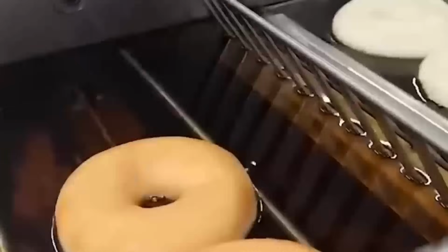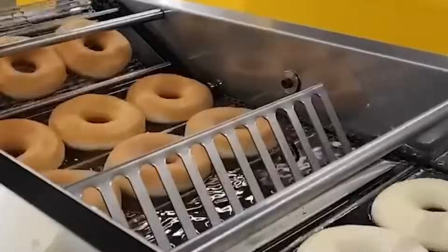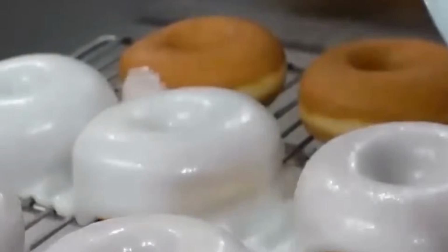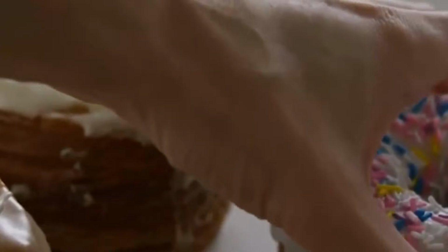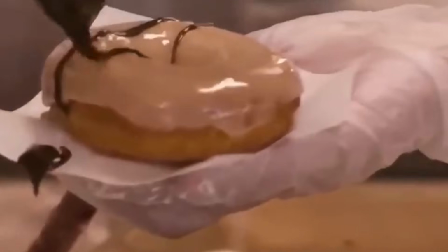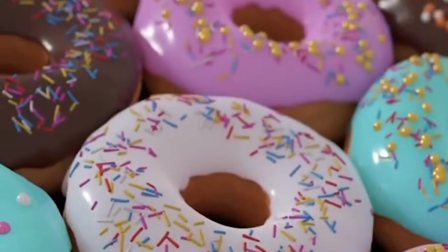Frying oil is a refined, high-stability vegetable shortening maintained at 185-190 degrees C. The fryer contains a dual-zone heating configuration and a submersion system using paddle arms that guide and flip the donuts midway through frying. Total fry time is approximately 90 seconds. Ring donuts are flipped automatically after 45 seconds by rotating bars. Filled donut bases remain face up to maintain a flat bottom.